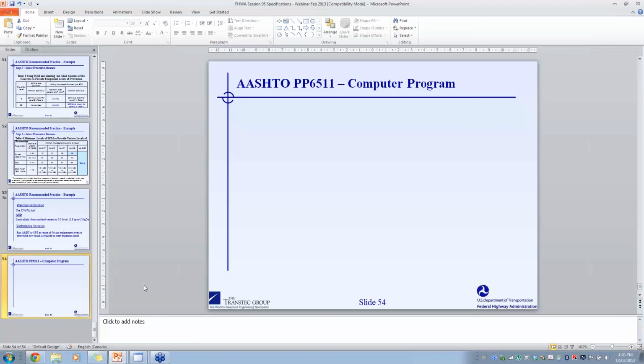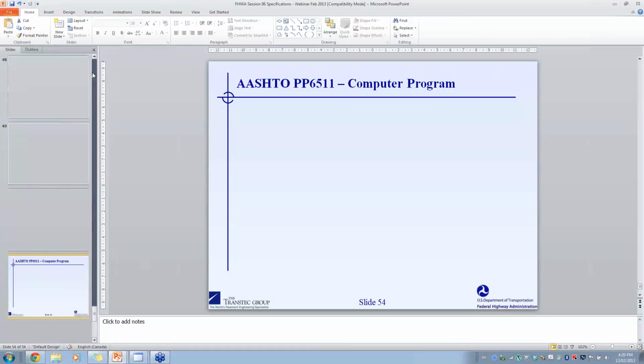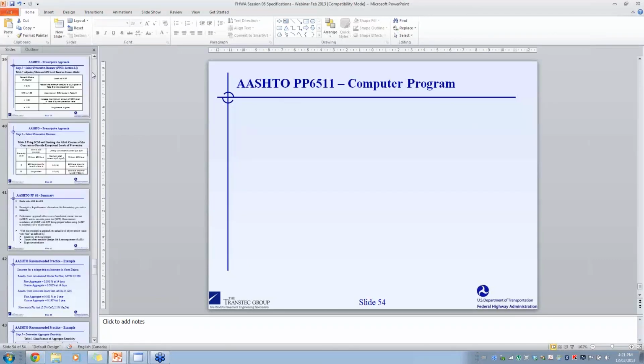Okay. The next question is, on the AMBT versus CPT plot, couldn't the upper range for applicability of the AMBT test for mitigation effectiveness be eliminated? It seems as if mitigation measures would be effective for an aggregate with a high AMBT expansion and a relatively low CPT expansion if the mitigation measure passes the AMBT test. Yeah, that point is frequently raised.